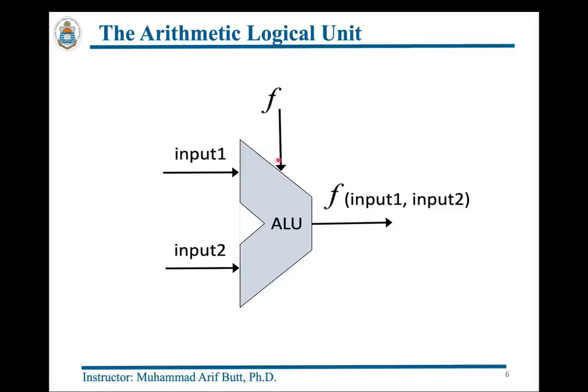The arithmetic functions performed by an ALU can be integer addition, subtraction, multiplication, division, and so on, while the logical functions can be NOT, AND, OR, XOR, and so on. Now, which functions the hardware designers want the ALU to perform and which they want to leave to the software layer is of course a hardware-software trade-off, and of course a major design decision as well.